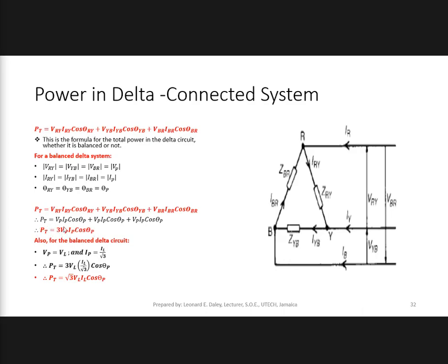For an inductive RL or RC load, you will not get everything that you put in, because some of that apparent power, and we'll discuss that in a little while, is going to be used up in the reactive part of the circuit. So it's also a measure of the amount of reactive power usage in a particular load.